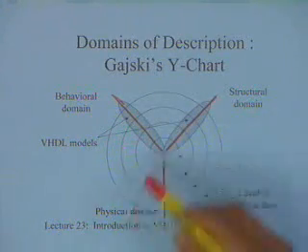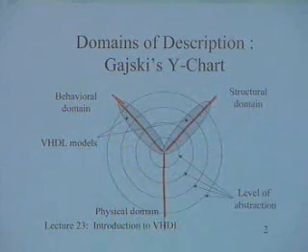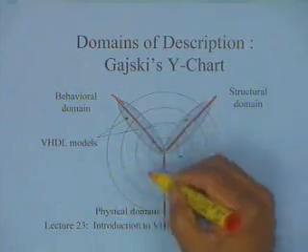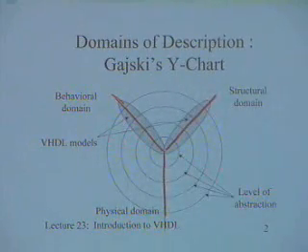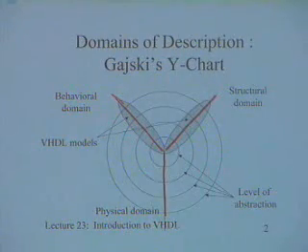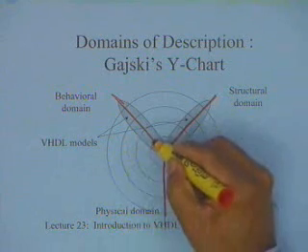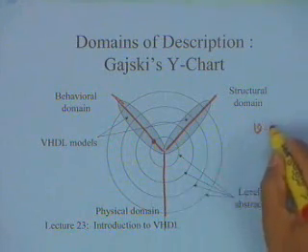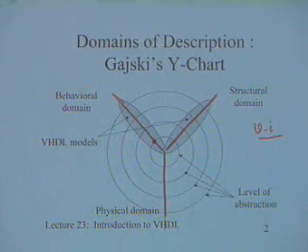See, what happens is, these are the domains, but even in these domains, you have various levels. You need not be representing your circuit at the same level. You can have different levels, and these circles represent the various levels of representation in the same domain. For example, after all, we know that all gates are built up using transistors. So this could be the functionality of a circuit represented as the VI relationship, the voltage-current relationship among the transistors. That's the lowest level.